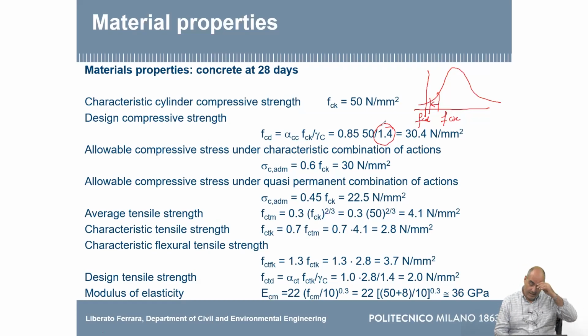There is another issue that Paul was mentioning. That is the size effect. We will just tackle it now. We measure our strength on cylinder specimens. Generally, they are 100 millimeter in diameter by 200 millimeter in height. Sometimes we also have 150 by 300, but this becomes impractical.